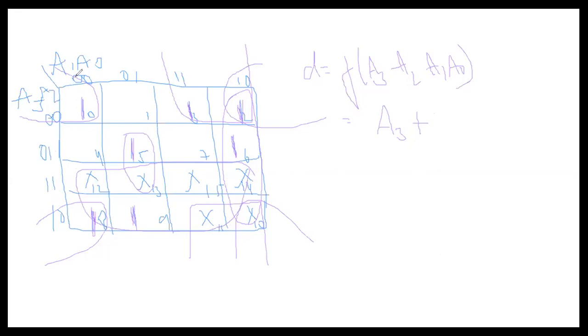the 4-box combination of the corner bits. In the corner bits you can see A1 changes from 0 to 1, A0 is 0, so A0 bar. And of the A3 and A2 MSB bits, A2 is 0, so A2 bar, and A3 changes from 1 to 0. We got the 4-box combination, so we get 2 literals. An 8-box combination means 1 literal only. Another 4-box combination we have is 3, 2, and 10, 11 with don't cares.